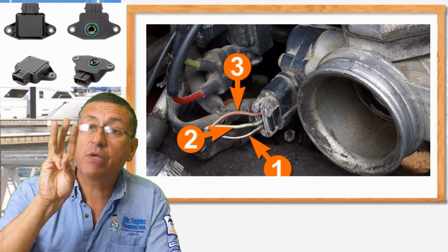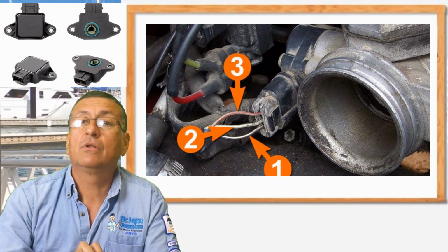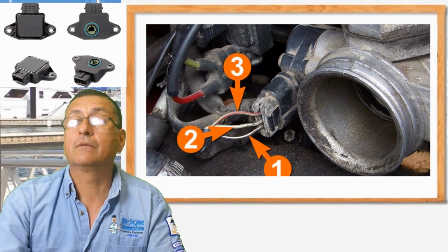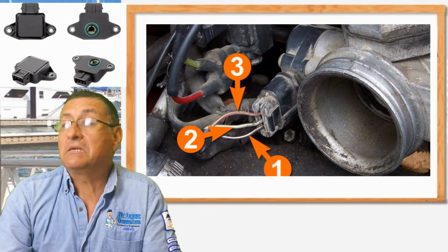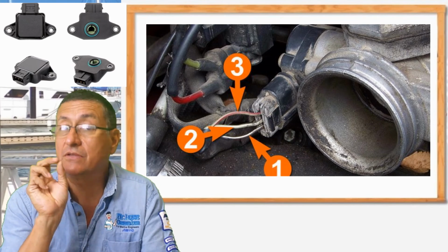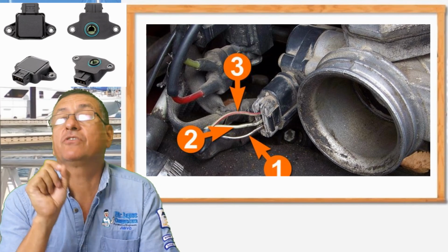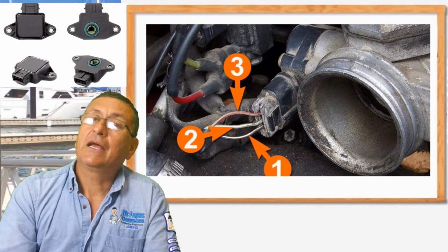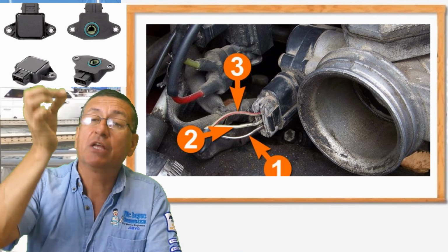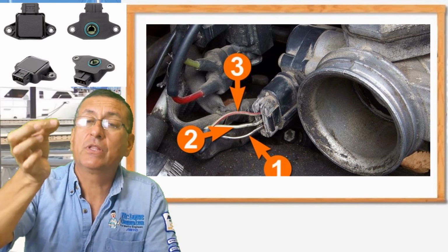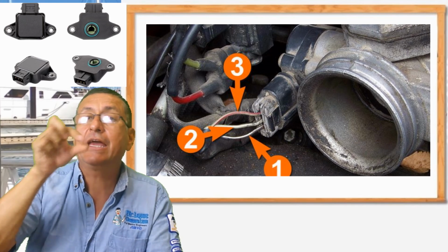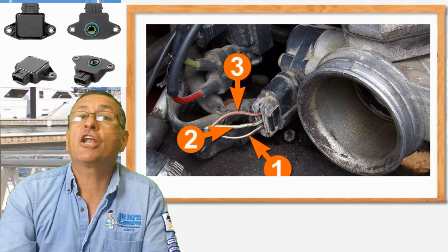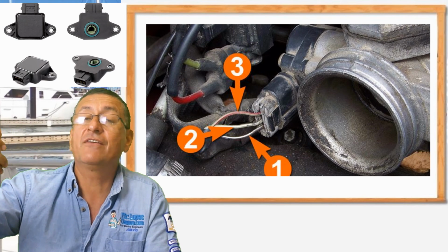With the engine running, it's important to identify in the throttle position sensor, normally, those sensors have 3 cables. One is the ground, the other one is the positive coming from the computer, and the other one is the signal. Punch the cable with a couple of needles, and connect alligators connected to your voltmeter. And with the engine running, accelerate the engine and verify the voltage.